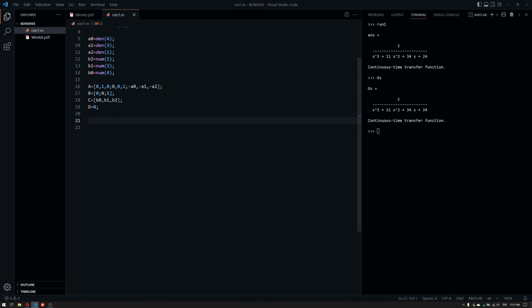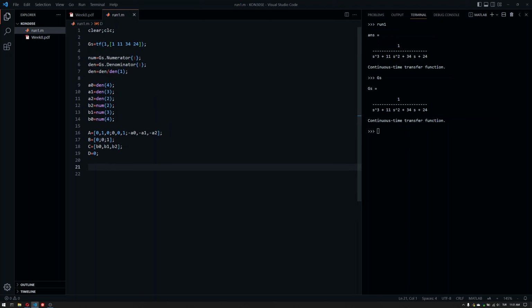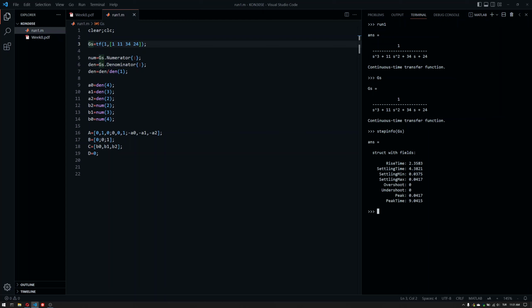So we're going to compute a step response here. Now for that, what we can do, of course, again, is to pick a settling time of G(s), using stepinfo, for example, on G(s) here, and see what the settling time is. In our case, I'm going to stick with 5, and again, I'm just trying to simplify the example here. But what you can do is just check the step info here. Of course, if you're in C, you are not going to be able to do that.